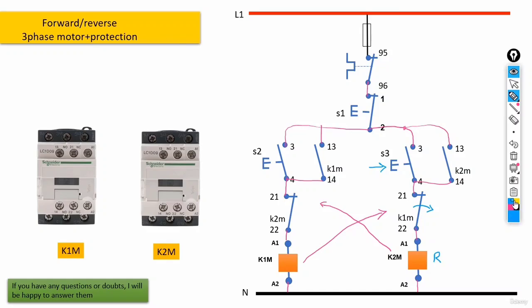Now, just like before, this time when the second contactor gets activated, its close contact that we set in this path would be opened. And again, just like before, from now on, we won't be able to use this start push button to activate the second contactor, which is actually the forward contactor. Somehow the close contact here prevents you from doing that. And well, obviously the same thing is happening in the other one. Alright, overall guys, this is what I meant by adding more protective equipments and devices to our control circuit.